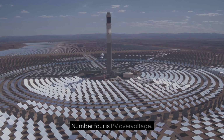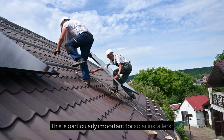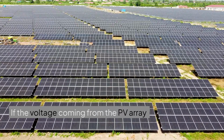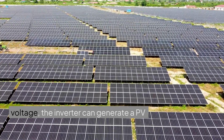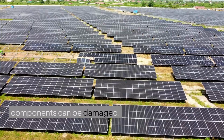4. PV overvoltage. Number 4 is PV overvoltage. This is particularly important for solar installers. If the voltage coming from the PV array exceeds the inverter's maximum PV input voltage, the inverter can generate a PV overvoltage fault and, in severe cases, components can be damaged.